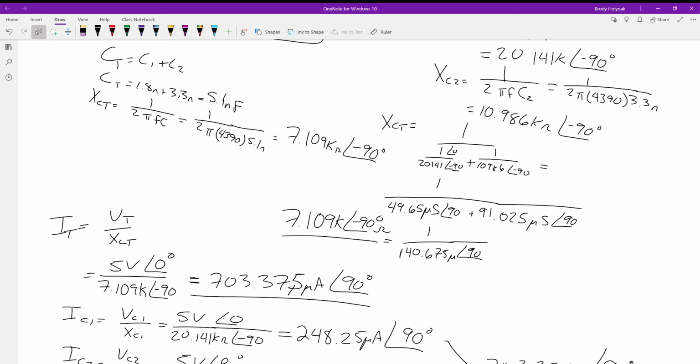We would solve for it and get the exact same answers except for the phase angles. They would be zero because the resistors do not react to phase angle. They do not care what frequency it runs at. That's the nice thing about resistors, they will play nice and stay the same as we shift frequencies. The rest of the components will react to the frequency depending on what it is.